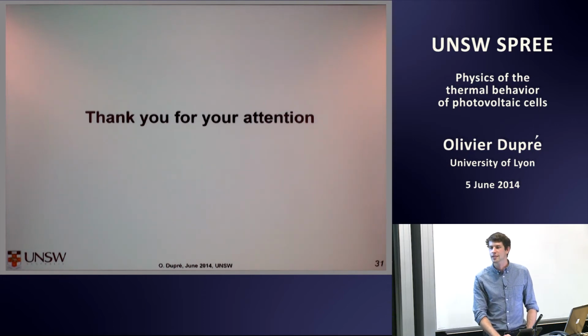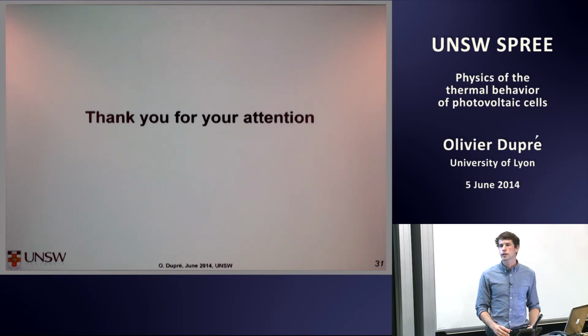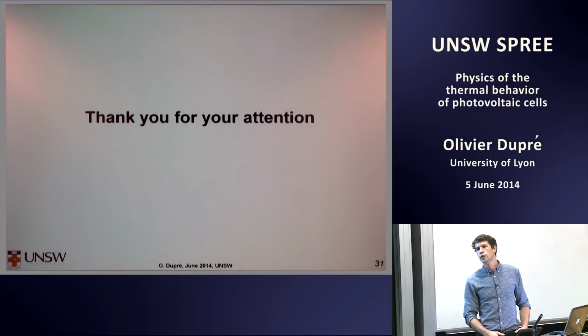Yeah. What spectrum did you use in most of the graphs, like over the bandgap? So for the first graph, where we were using the analytical approach, we're using a black body at 5,800 K, and then afterwards we have used the AM 1.5 spectrum to show the impact of the spectrum and the temperature coefficient.